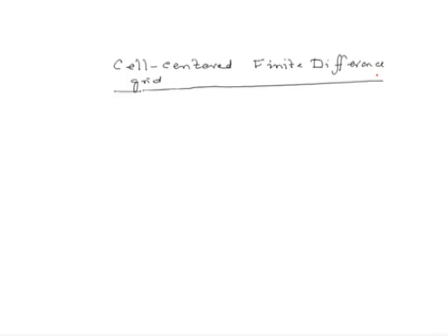Let me illustrate it using our 1D problem. In one dimension we have a simple one dimensional domain, and for discretization we divided it into, let us say, n equal segments. The segments could be unequal, it did not really matter. Now, previously, these were the nodes, that is the points which mark our divisions, those were the ones which we had taken as our grid points.